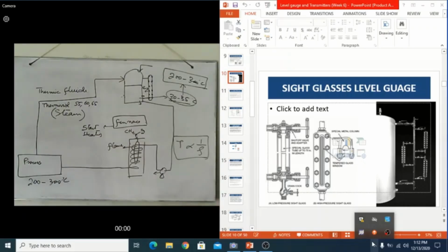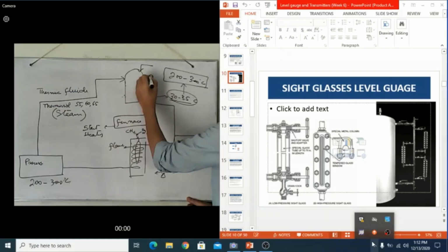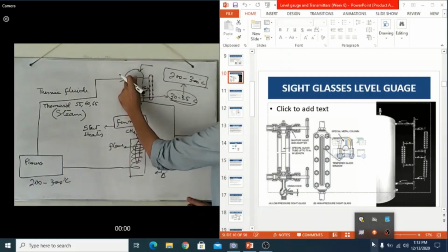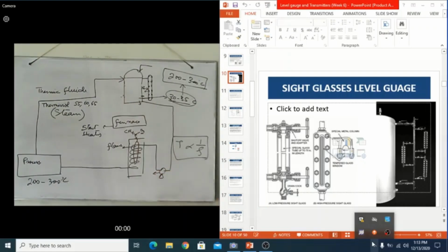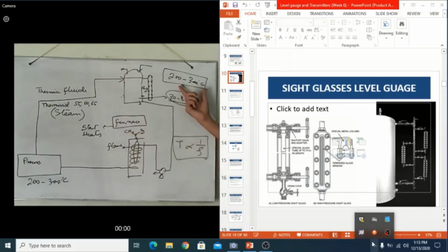On the other hand, if its volume increases to that much height that your last bolt is still dipped in the tank, it means it can overflow your tank. Why? Because a certain change in temperature may cause an increment in the volume of the liquid which is present in the whole circuit.